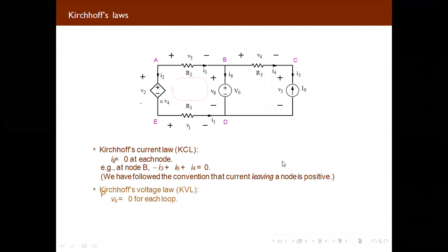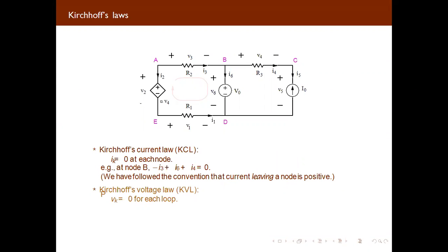What we are saying is, the voltage potential drop across each and every element, if we take the summation of that voltage, that will be 0 for a closed loop. And a closed loop is nothing but a loop. If the current flowing from any point has a return path to come back, at that time we call it a closed loop.